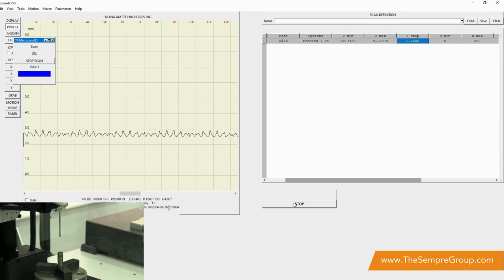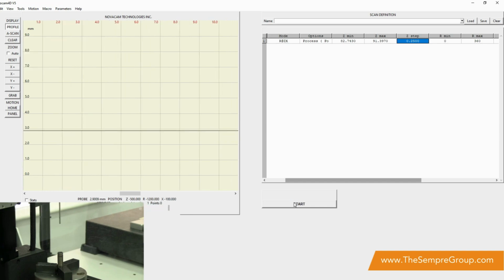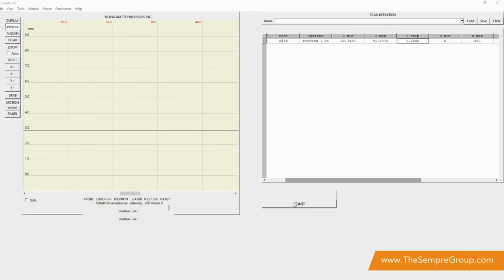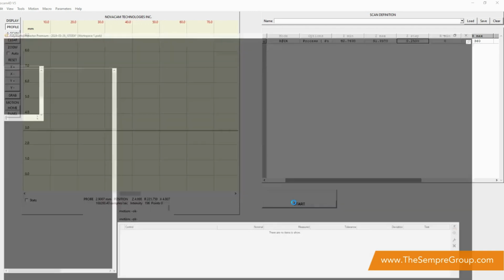When it completes, the probe drives out of the internal bore, and what we'll see now is a point cloud data set from our scan. This goes straight into, in this sense, Polyworks, whereas we can process the data in lots of other software. Effectively, we're using this system to obtain a high accuracy point cloud, so what we do with that, we're relatively flexible with.